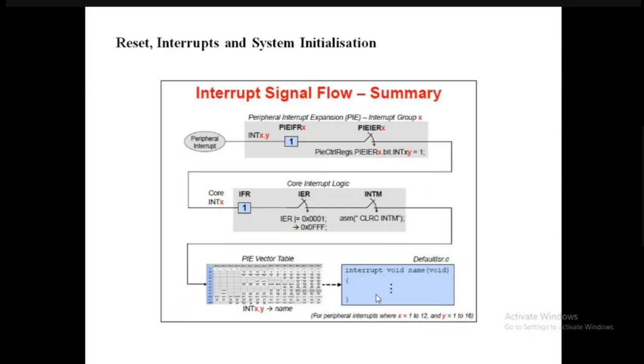Because once you know, you can take an example. Let's say you are injecting a certain signal into your board, and it's a periodic signal, with the help of ADC. So it is repeating after a certain period of time, and now you want to do a certain operation on that signal. With the help of ADC, if you call an interrupt, after a certain interval of time that interrupt will come, and whatever operation you want to perform on that signal, where you want to reduce your duty, where you want to increase your duty, you will be able to do in your interrupt service routine. So once you understand interrupts, it will be very easy for you to model any of your algorithms.